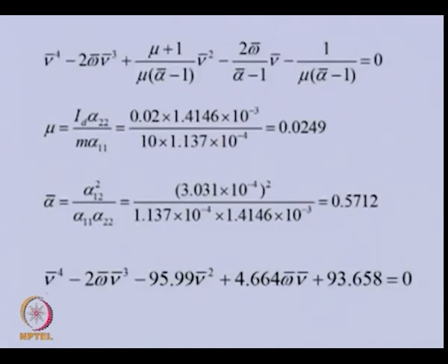If we recall from the third lecture, when we considered the general motion of a disk, this was the frequency equation we got, in which we had the non-dimensional spin ratio, coupling effect, and disk effect. These can be calculated for the given values, and if we substitute them in this frequency equation, we will get a polynomial like this.